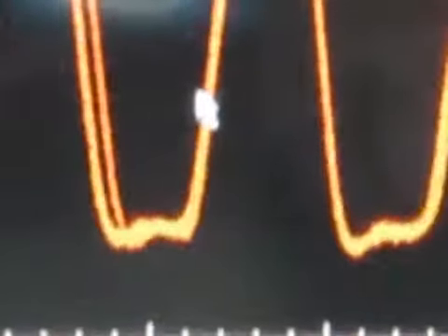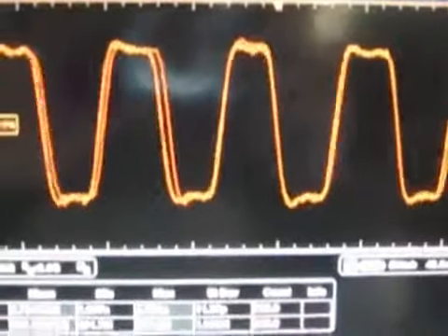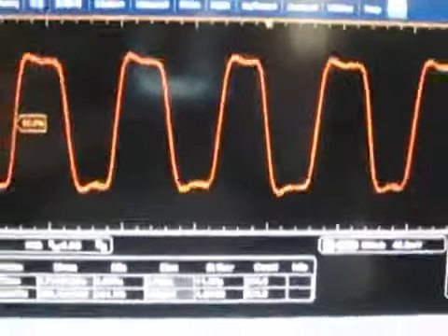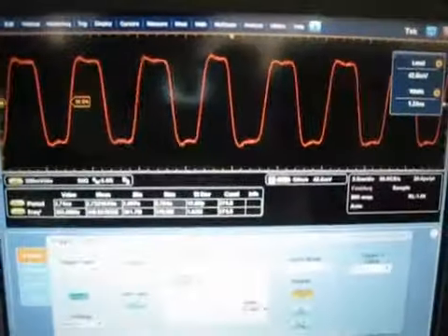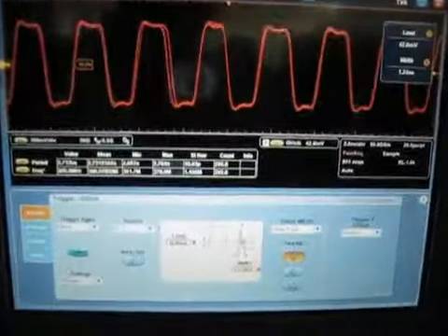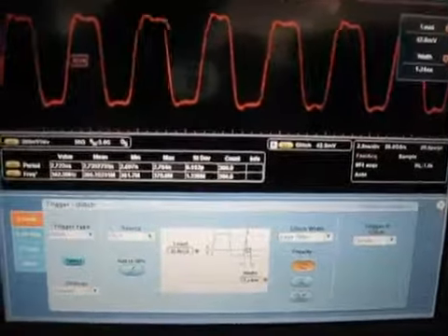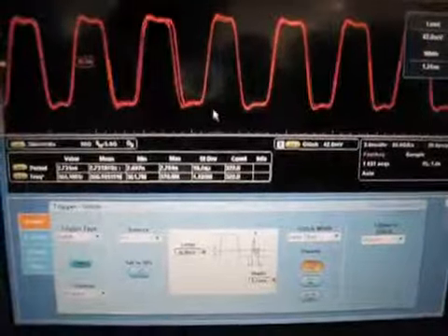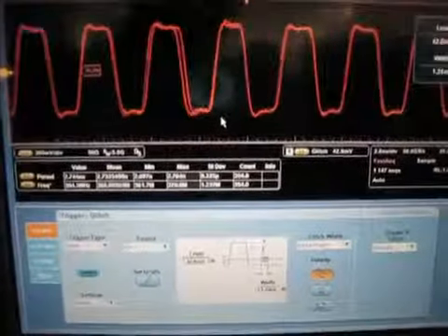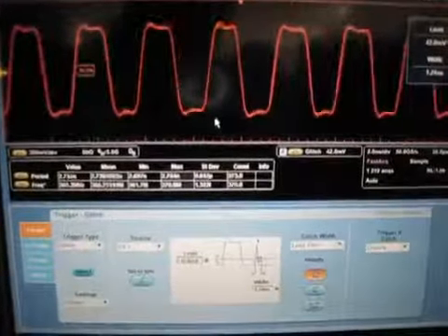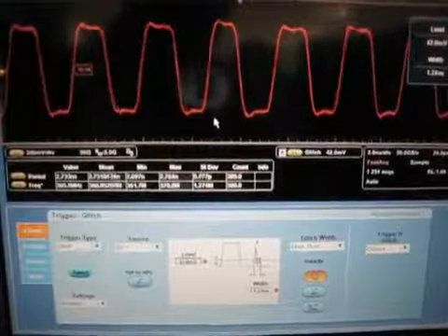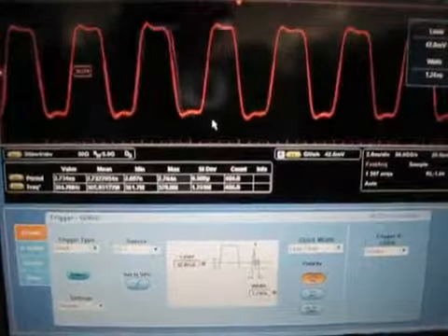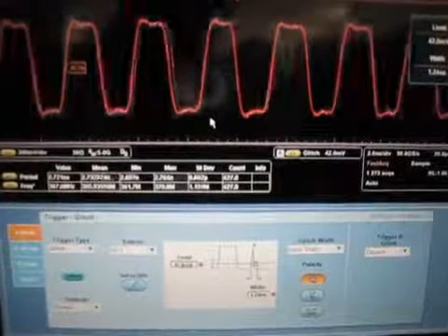This will finally cause the system to crash during real application running. Because we have these DPX tools, we can easily identify the problem and then set the advanced trigger to trigger on this issue. So I think this is a pretty good example to show how efficiently we can use the scope to isolate the issue.